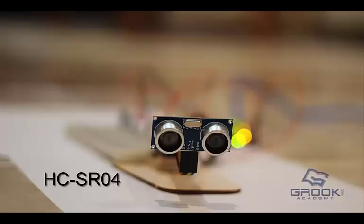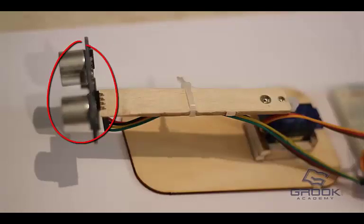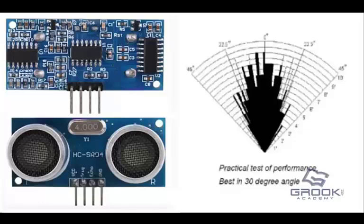Second component is the ranging module HC-SR04, which provides 2 to 400 cm non-contact measurement function. The ranging accuracy can reach 3 mm. The module includes ultrasonic transmitters, receiver, and control circuit.